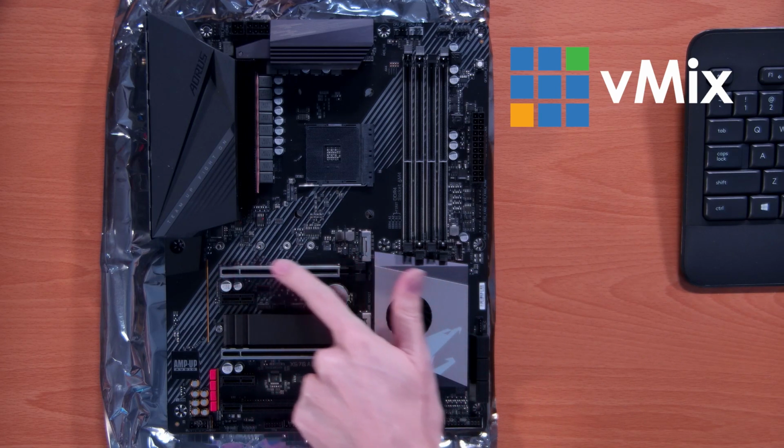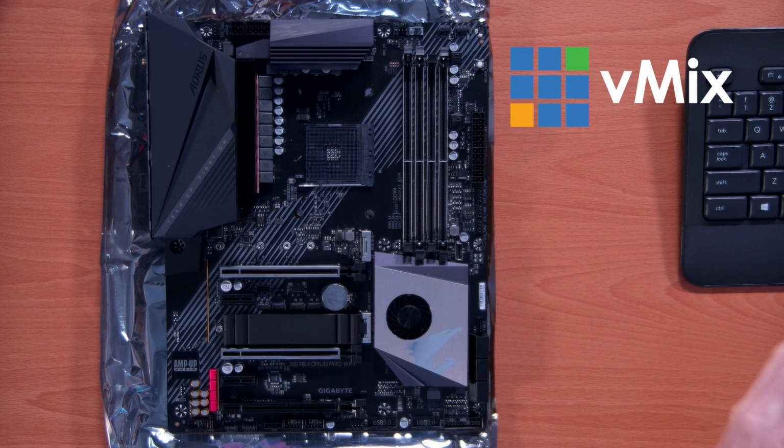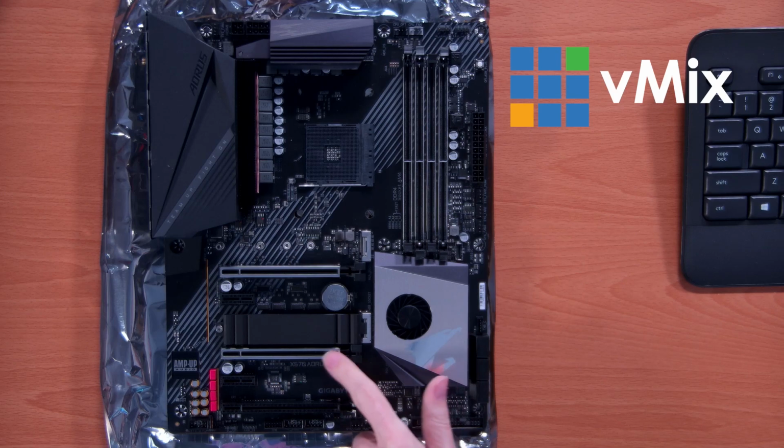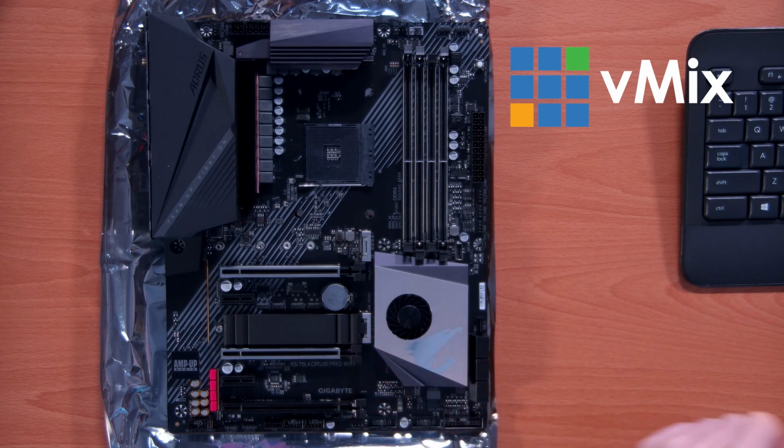Typically the top one here will be a by 16 lane slot, and that's where you put your graphics card. Usually most of the data transfer is to that slot. This slot here is a by 8 lane slot, which means that I could install a capture card like this Blackmagic one that requires by 8 lanes to function properly. The tricky thing is that sometimes you don't get these dedicated lanes. Sometimes they're shared across different slots. So it's important to make sure with your motherboard manufacturer that you have dedicated lanes to the slots that you need. That's very important.